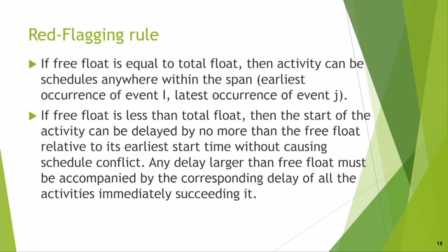You should always remember this red flag rule: if free float is equal to total float, then the activity can be scheduled anywhere within the span, that is, between the earliest occurrence of event I and the latest occurrence of event J. If free float is less than total float, then the start of the activity can be delayed by no more than the free float relative to its earliest start time without causing schedule conflict.